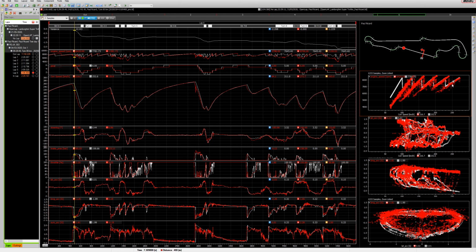But you will also notice that as we go to higher speeds, it looks like the real car has a bit taller gearing. Although I have used the same exact gear ratios for the model, the thing that I keep constant but reality doesn't is the tire radius. So downforce and centrifugal forces due to the rotation actually change the diameter of the tire, and this is why such differences may appear.